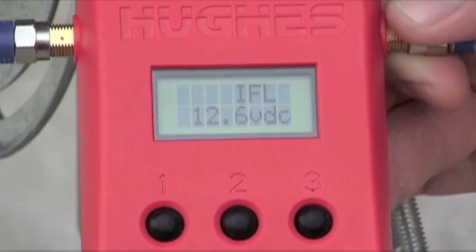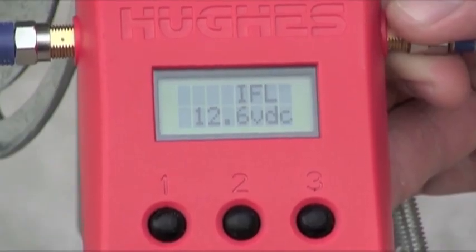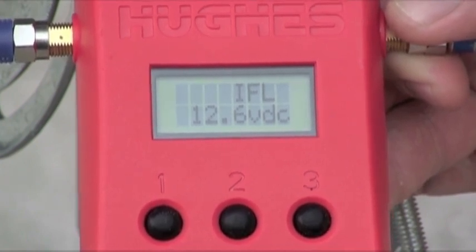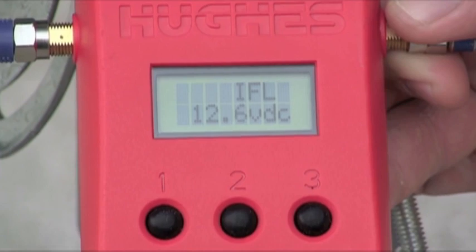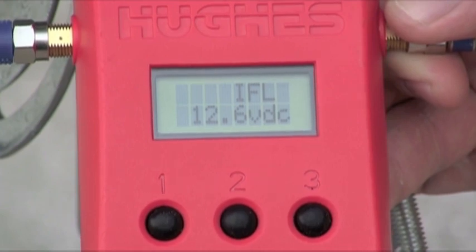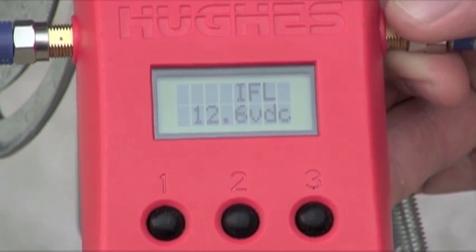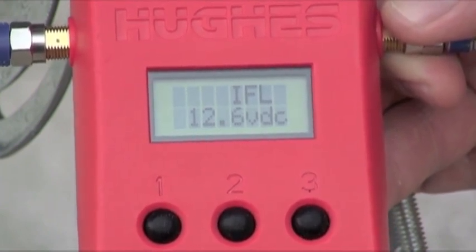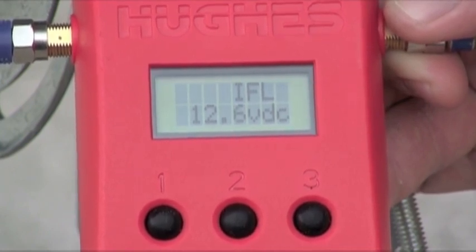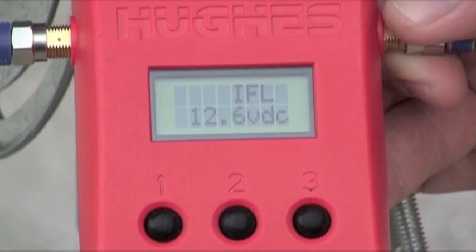Okay, to begin the pointing process, the first step that we did was to preset the elevation, the tilt angle, and the polarizer according to the pointing parameters given by the installer laptop. The next step is that we put the DAPT in line on the receive side, going from the IDU to the LMB with the DAPT in the middle, and that allows us to communicate with the laptop and not have to walk back and forth to the laptop.